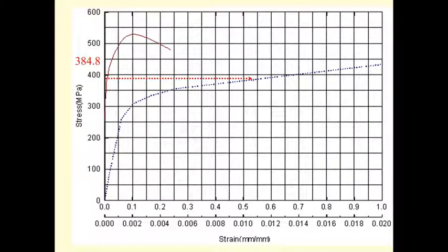Then project it back, and you may estimate the strain here to be 0.0108. It's not 0.011. Okay, 0.011 is here. It's very close to it. You do the proportion, you get 0.0108. This is going to be the strain of the portion BC.